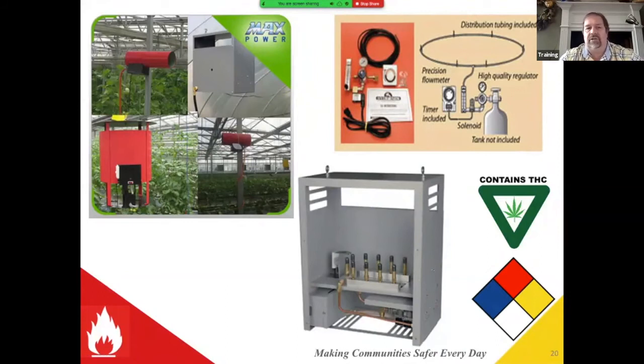The problem is combustion byproducts are not merely CO2, heat, and water. They also produce NOx and CO. So carbon monoxide, the silent killer, and NOx is very highly toxic. And out of the box, they produce a certain ratio. So carbon monoxide discharge may be lower when they pull this thing out of the box and install it on the first day. But every day thereafter, as these burners become dirty and get a little bit of dust on them, the ratios become skewed from the original delivery, and they produce high ratios of carbon monoxide and NOx, especially if not properly cared for. Easily send people to the hospital, if not death.